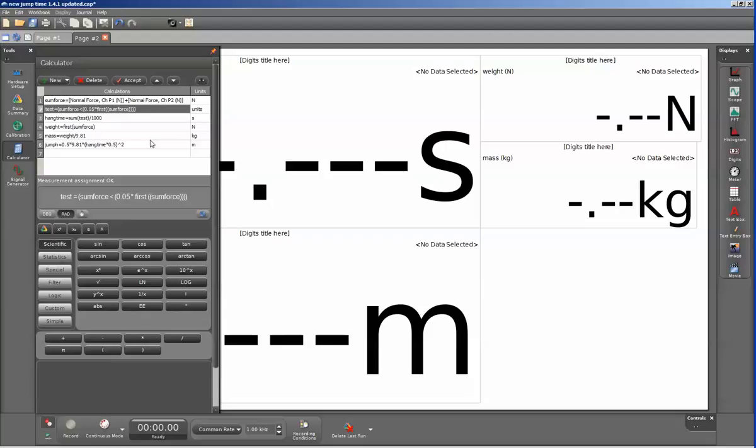There is a certain amount of ringing in the force platforms, so that sometimes there can be some variation in forces even when the subject has left the surface. So this value can be adjusted to make sure that you're getting the best values.